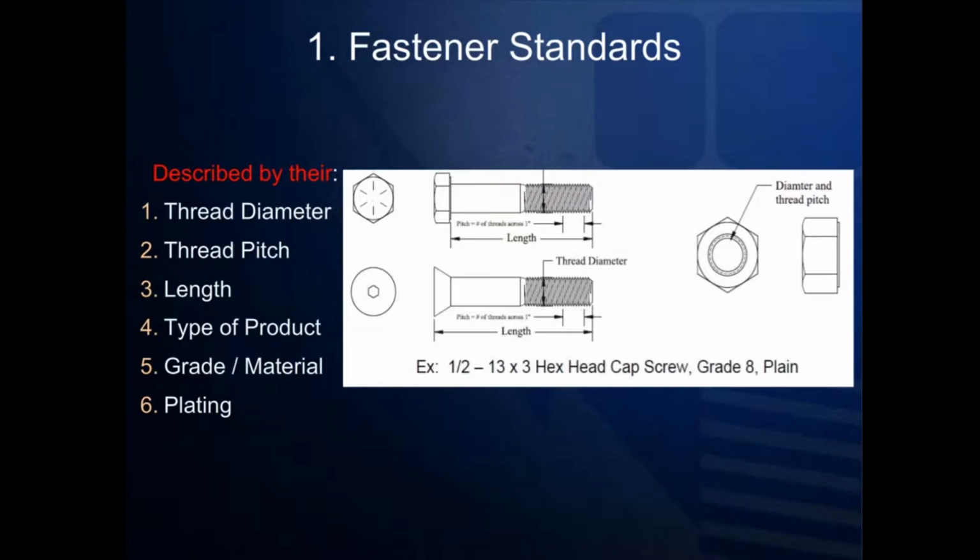Keep in mind that due to the Fastener Quality Act, all fasteners except for low-carbon steel such as grade 2 or A307 are required to be marked with the manufacturer's head mark and also the designation indicating what grade or material the fastener is made of.